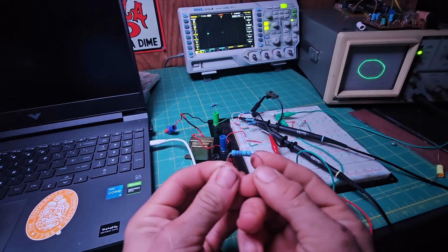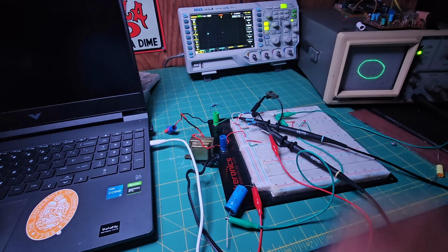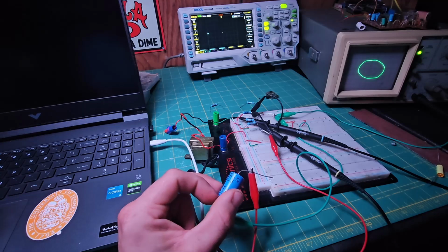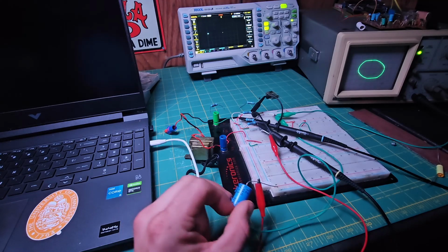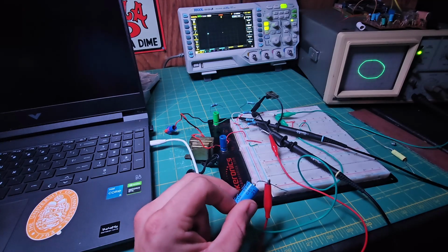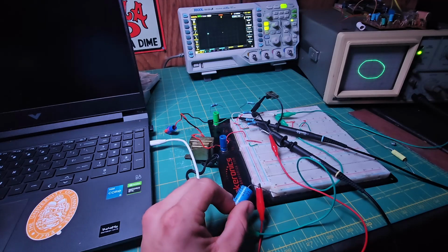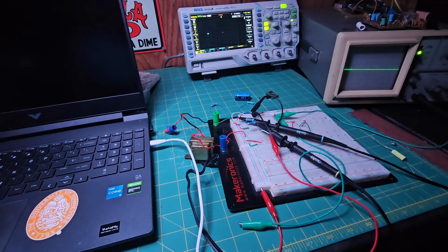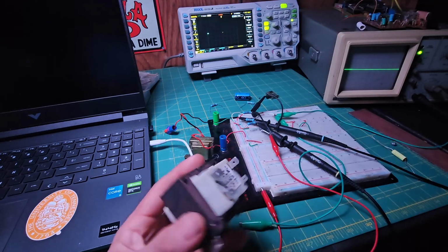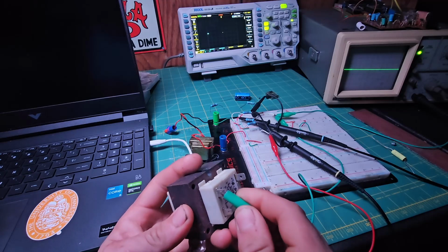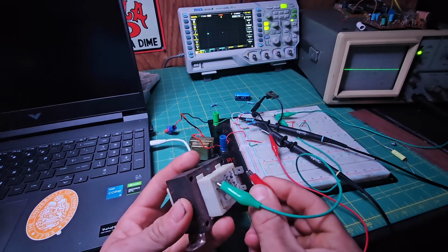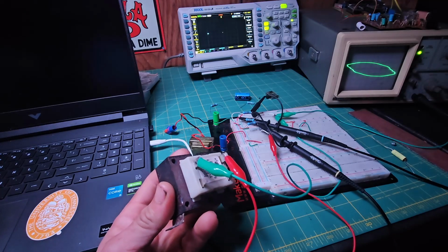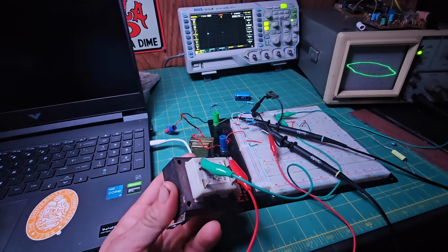So resistors are linear devices. The current flowing to them is just described by Ohm's law. Now capacitors, it still is described by Ohm's law, but it's a little more complicated. They do not flow the same amount of current all the time. That's why they call them a reactive component. Inductors and capacitors are reactive components, and we can check a transformer right here. Let's look at the primary side, because that will be the side that has the highest inductance value. And you can see as well, inductors are very similar to capacitors. They are reactive components as well.